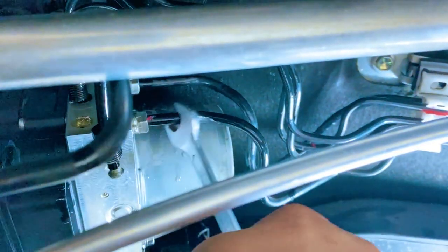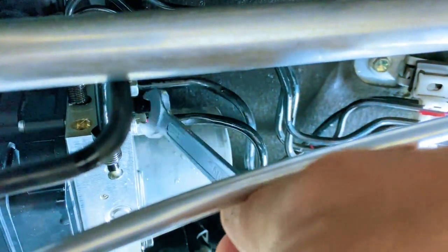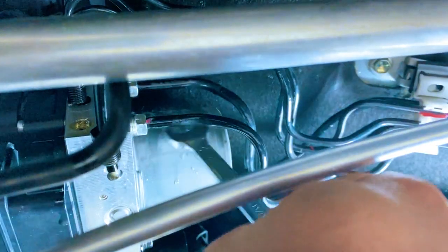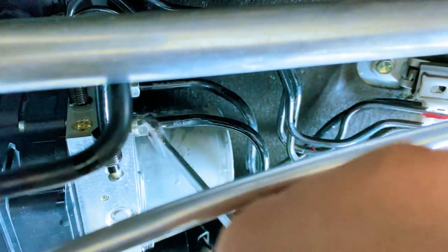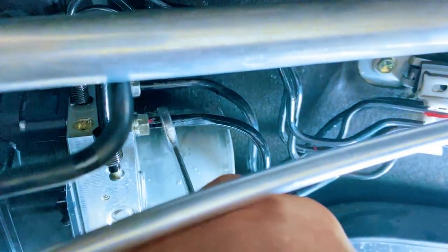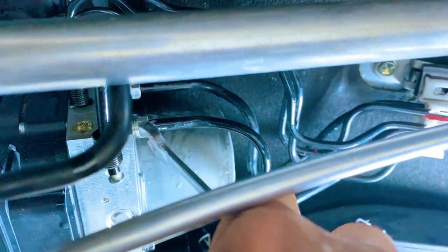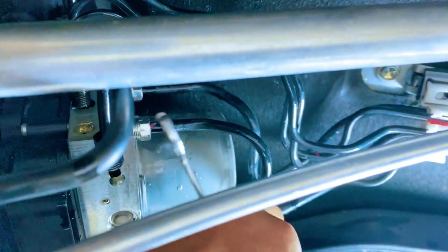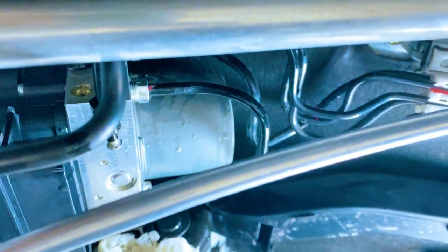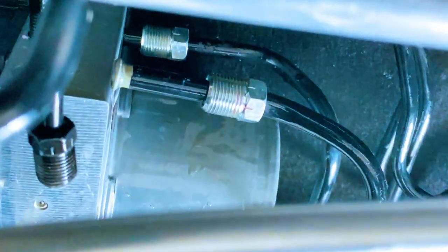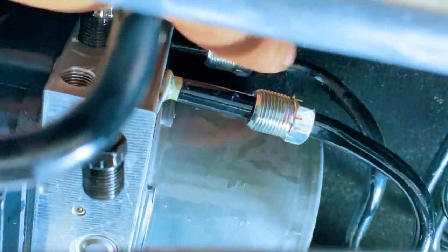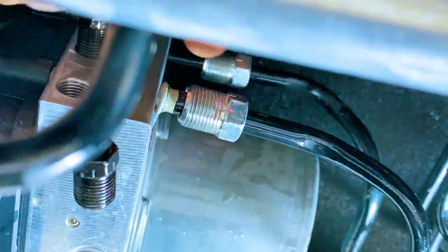When the vehicle activates ABS, traction control, VSC, brake hold, or brake assist, the skid control ECU commands the ABS motor relay. The relay then operates the ABS pump motor. So when we have an electrical fault involving the ABS pump motor, the diagnosis can lead directly back to the brake actuator assembly. This is why the Toyota repair manual lists the skid control ECU, which is integrated with the brake actuator assembly, as the trouble area for these DTCs.